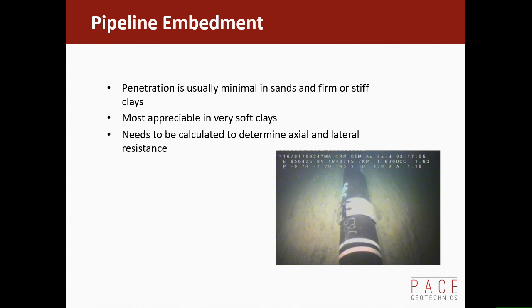and it's something we need to understand to determine the actual axial resistance and the lateral resistance as well, because obviously if you've got it embedded, it's got a greater contact length, so that gives it more cohesion of the clay soils, if you remember. And the partial embedment also stops it moving sideways so easily.